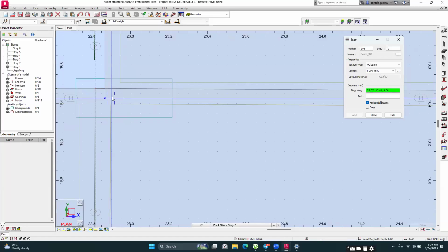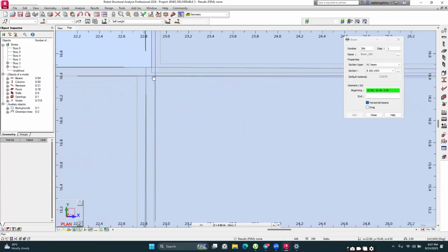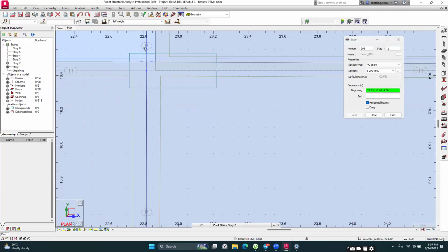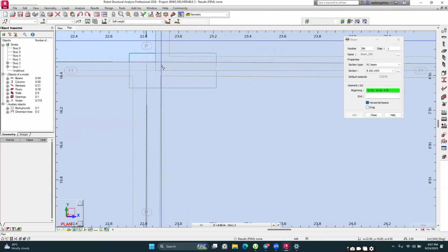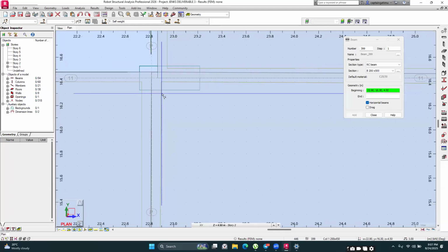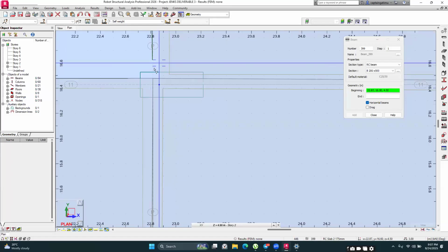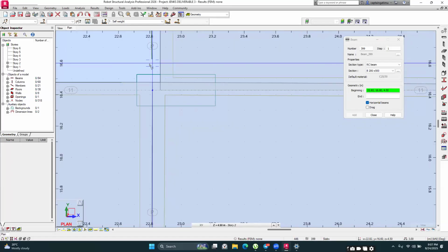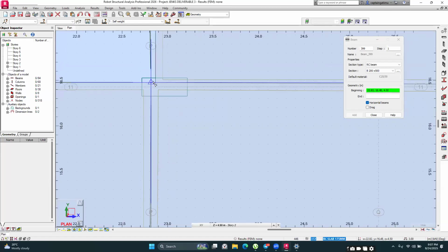And this is what you have to be careful with in these kinds of things. Try to ensure that the columns or the beams that join in your columns are going to these nodes here and not to these other nodes that may be formed as you model the beams. Having them along the axis, say this axis in this direction and this axis in this direction, makes your modeling easier. Otherwise it will create a lot of eccentricity in your column design.